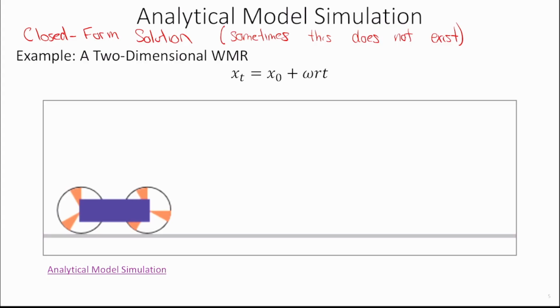So whenever your simulation gets more complicated, let's say you do care about sensor noise or you do care about wheel slippage, you're not going to have an analytical model for that type of scenario. Something that tells you from a single invocation of a function what the change in configuration might be. But if we're looking at this simple little robot here, which just operates in this one-dimensional plane, line, I guess, then we can get away with this really simple closed-form solution.